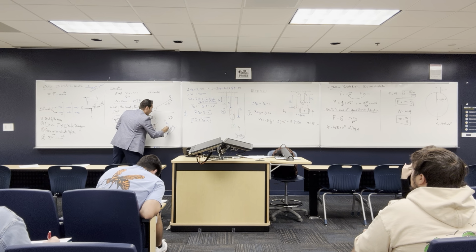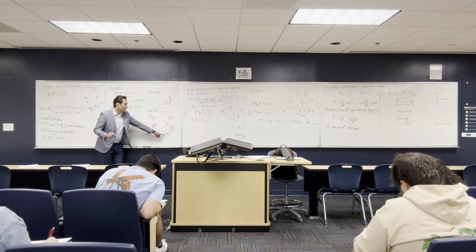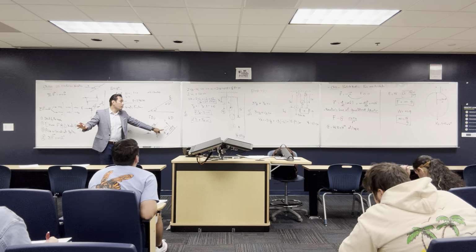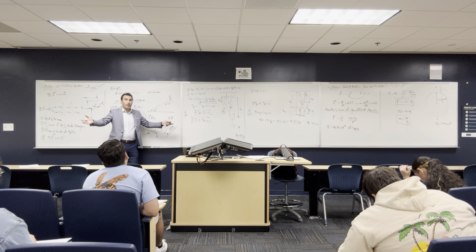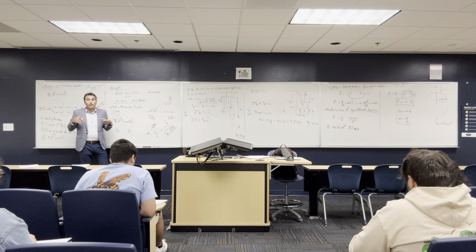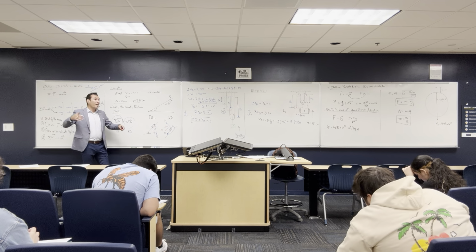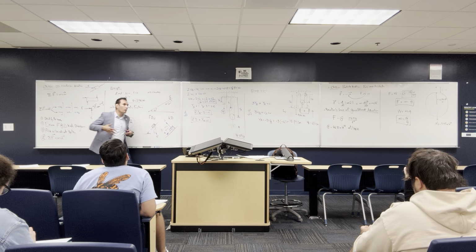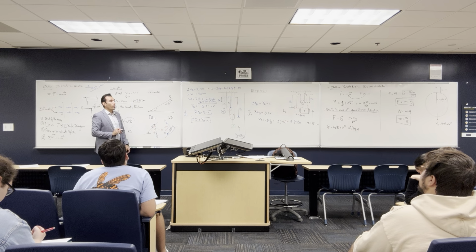Here is ma, the direction of the acceleration. So the kinetic diagram is the axes and the direction of the acceleration. You can assume the acceleration in the other direction, but I assume based on common sense, on engineering sense. This body is going down and gravity is down, so it is always accelerating downward, not upward.